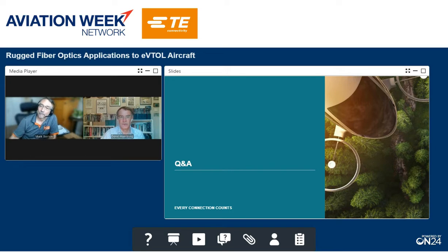Right. So when you're talking about rugged fiber optics, you're talking about rugged to vibration as well as other things. Vibration, thermal shock, temperature cycling. There are hot and cold storage limits requirements that can be minus 55 C to 125 C. Sometimes you will see transceivers rated minus 40 to 85. But the customer may have a cold start situation where it has to start even colder than that. It might not necessarily meet the data sheet that cold, but it may have to power up and operate while the unit comes up to that minus 40 temperature. So there's a lot of demanding requirements that these systems have met.